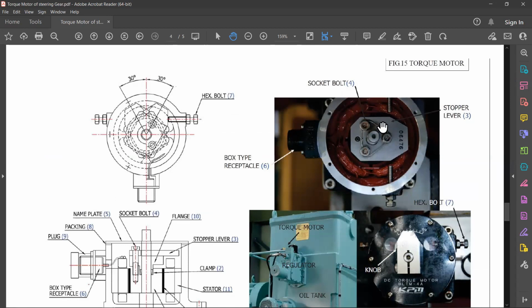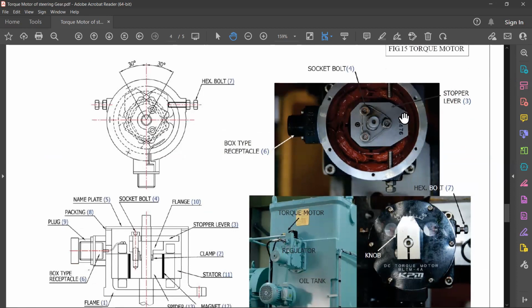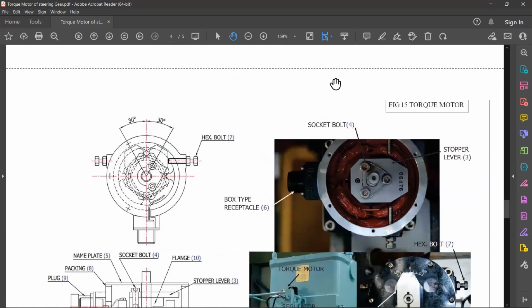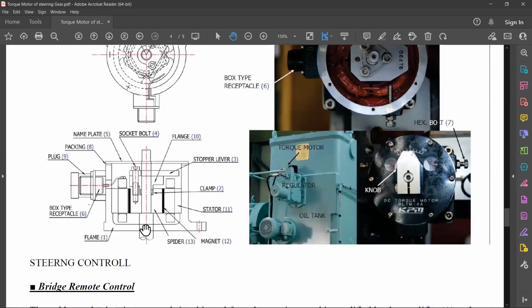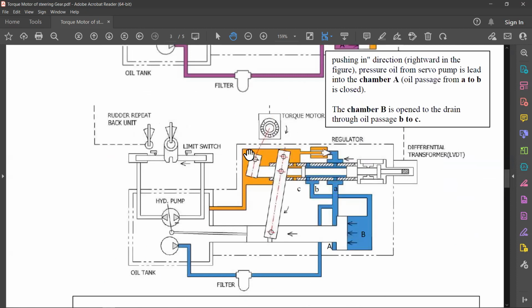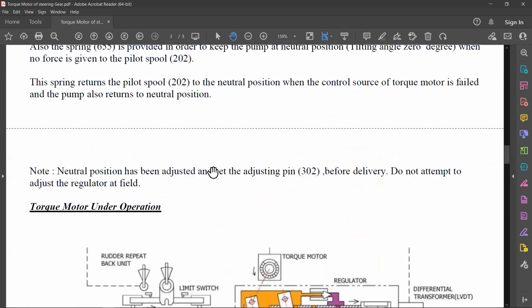The motor is basically controlling the operation of this stopper sleeve. And what this stopper sleeve is connected to at the bottom side is a small piece, which is a stopper sleeve piston, and it pushes or pulls this entire spool piston. Okay, basic idea is the same.